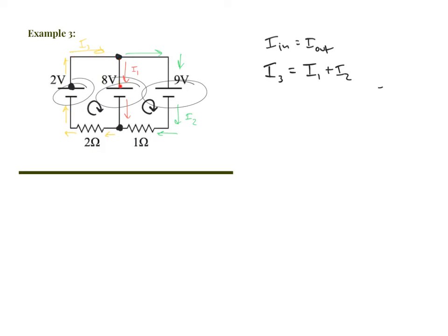Now, as I move along this circuit, I'm going to get to an 8-volt battery. As I move through this 8-volt battery, I'm going against the battery, which means I am losing potential through the battery. I'm going backwards through it, essentially. So what I will write down is a negative 8 volts. And actually, I'm just going to leave off the volts for now. I know that's bad form, but I'm going to do it. And then I'll keep going through the circuit.